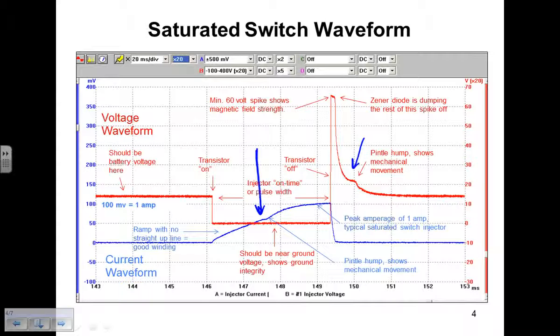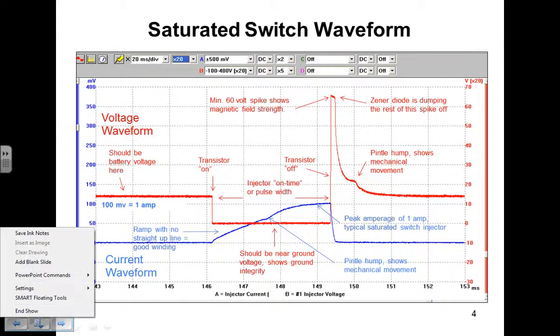So then you got to account for this too: if it looks different, was that injector ever changed? Is that the same injector? Because even a new injector, reman or aftermarket component, can have a different position on where that hump's going to sit. But to give you an idea of what I'm talking about, how I use that, at the end of my fuel injector testing section,